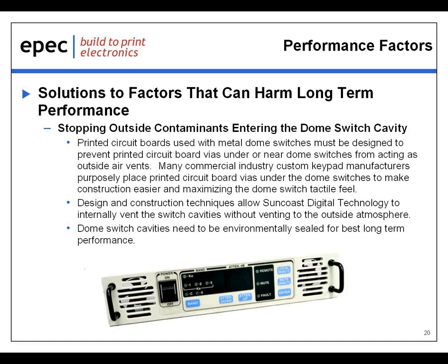Now, consider a toy air-filled balloon. When you press on the balloon, it presses back with increased force. In the same way, air in and around the tactile dome switch, or the dome switch cavity as we call it, will press back just like a toy air-filled balloon if the dome switch is sealed. Sealing the dome switches can reduce the tactile feel.